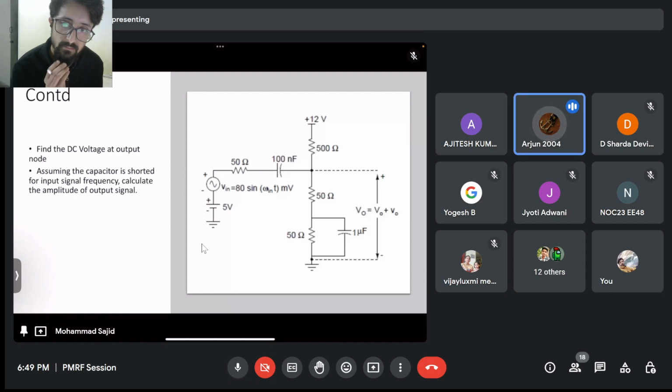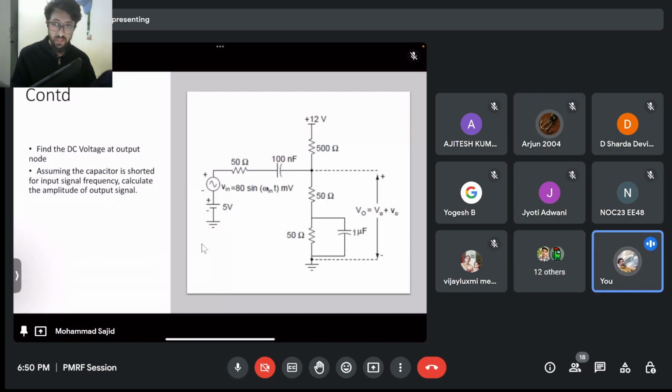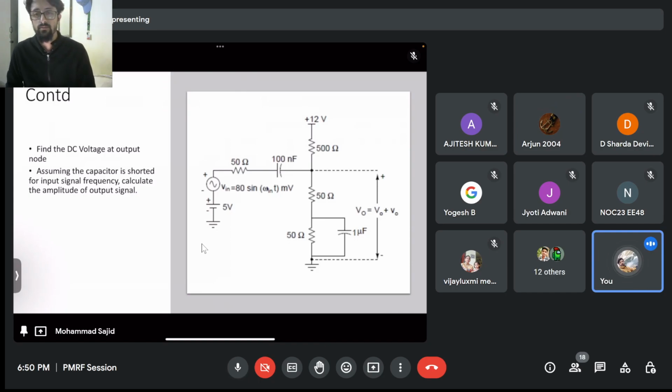Sir, we will remove all the voltage sources and ground them. Why do you do that, and how do you think the final result will be the exact result? Which principle do you follow? Sir, we are following the superposition principle. Yes, right. The superposition principle says that if you have AC sources and DC sources, you can find individual answers by using DC separately and AC separately, right?